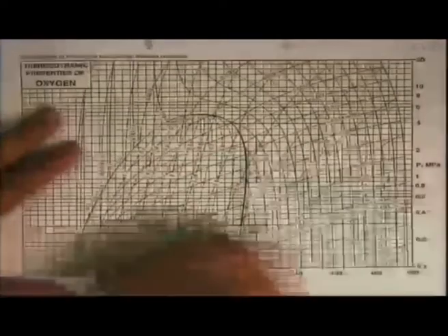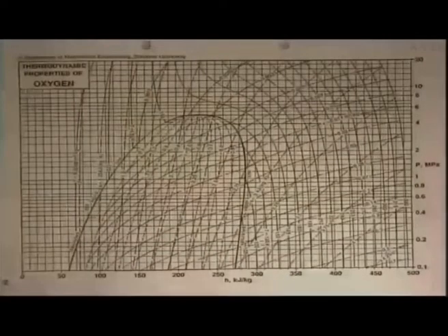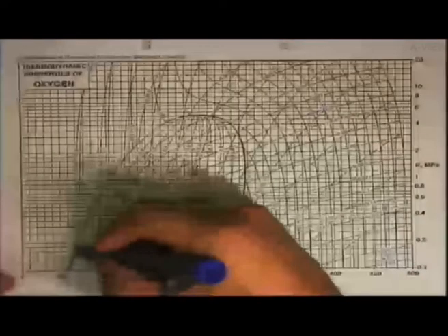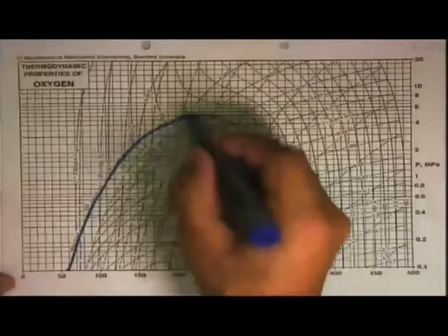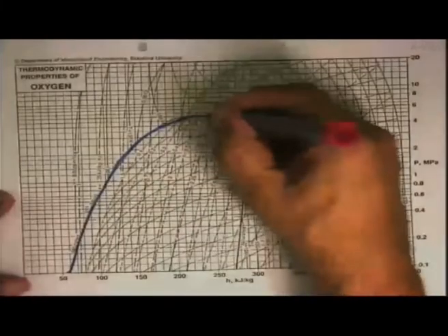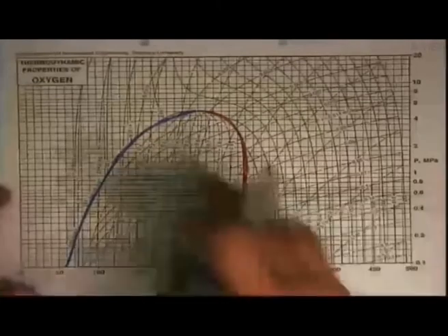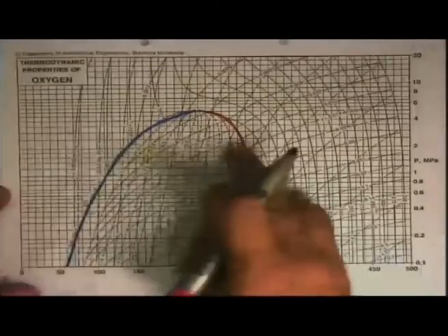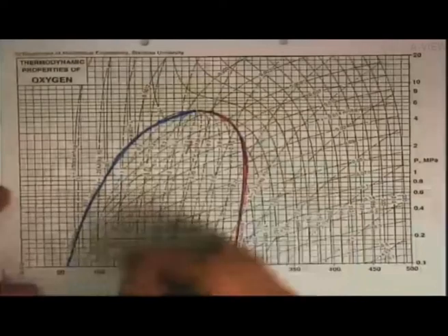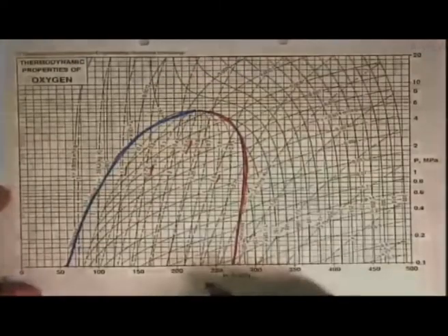And same thing we see here, saturated liquid line over there, saturated vapor line over there, just like what we had seen qualitatively there. So this is your saturated vapor line, and on the other side, we end up getting the saturated liquid line. Inside the dome, we have similar things, 0.1, 0.2 like this. This is constant dryness fraction over there. Then 1.5, 1.75, these are all constant specific entropy lines.